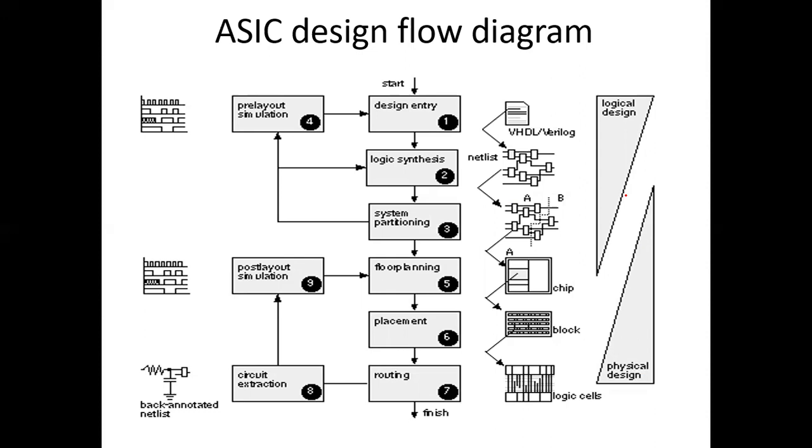But before that, we do the circuit extraction, and finally we check the post-layout simulation. If there is no error, we complete the flow and we get the ASIC design chip.